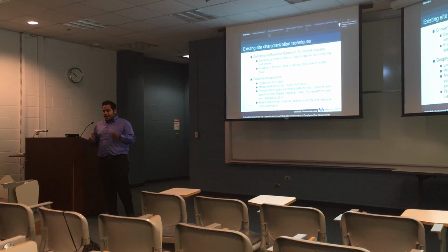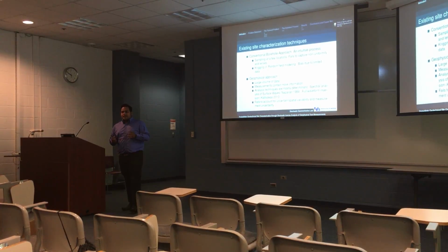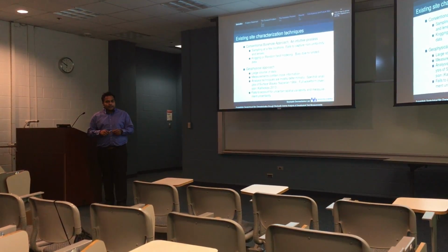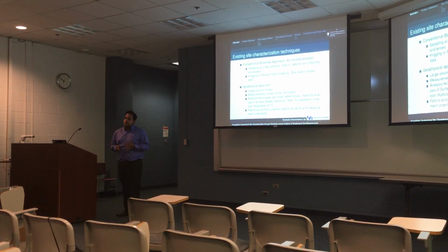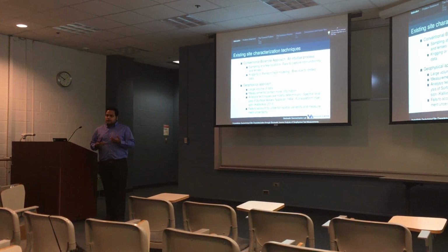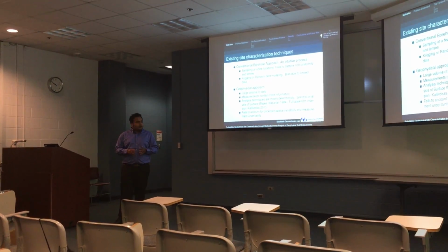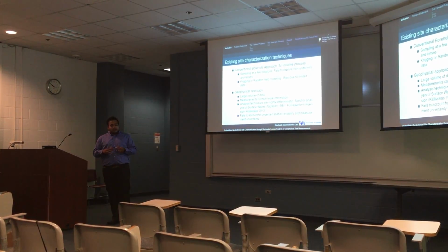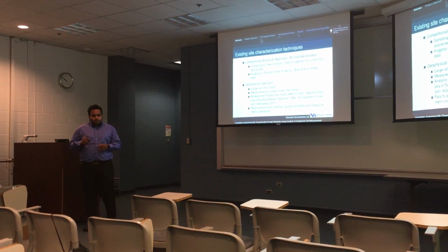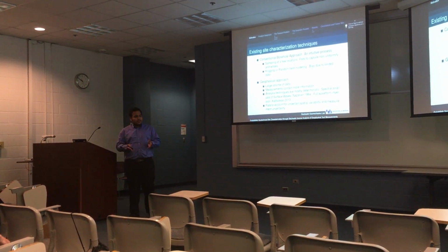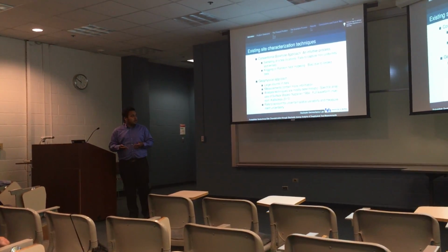What we do is we have a wave creating source on the surface of the soil. There are sensors located at a few spatial locations. The sensors measure the wave that propagates through the soil, and several properties of the waves. This produces a large volume of data because it is fairly inexpensive. The measurements contain more information. This is because the waves travel through all these non-uniform layers, they travel through all the lenses, and hence they get reflected, and so they contain a lot more information.